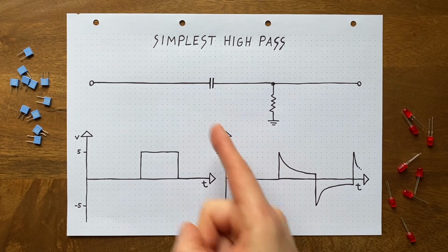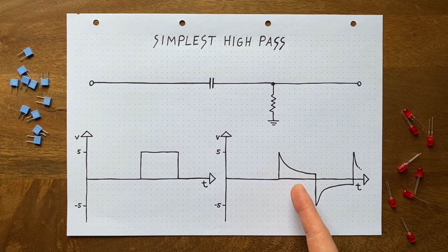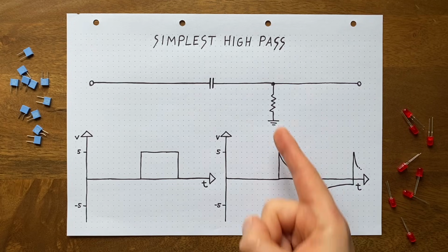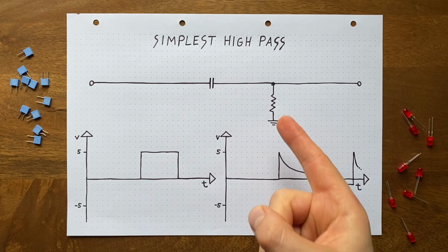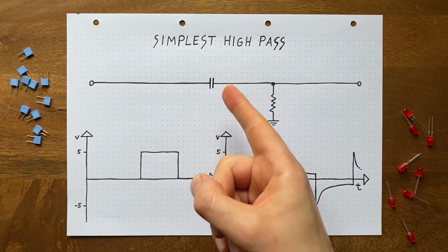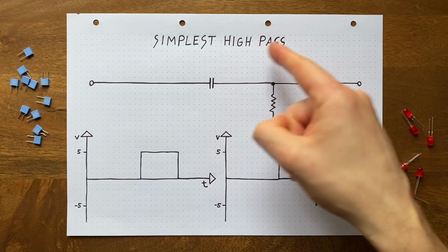But while the pressure stays high here, it will start falling over here since the excess water begins draining out through the resistor. The speed of that draining process will again depend on two factors: the capacitor size and the resistance value. The bigger the balloon, the more water it can displace, keeping the pressure here high for longer.